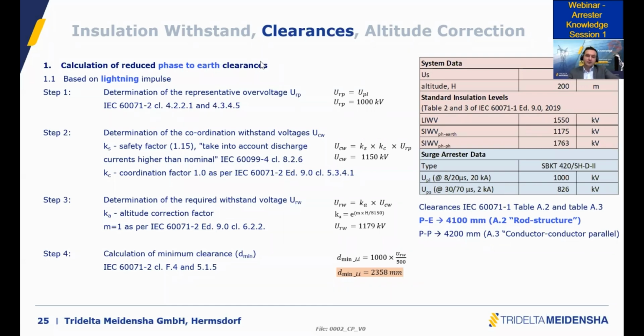So the manufacturer should look back at the tested value in the lab and confirm the required lightning impulse and switching impulse for the required altitude. But of course, in that case, you are just applying a factor on the tested value.